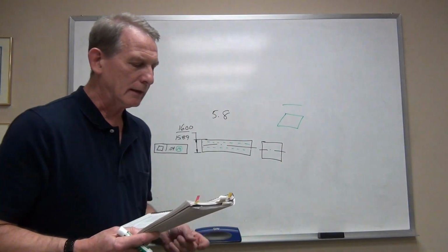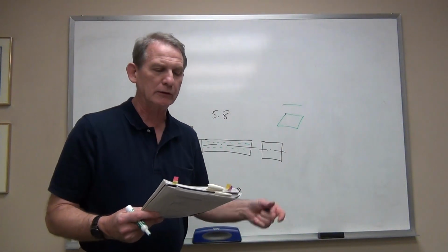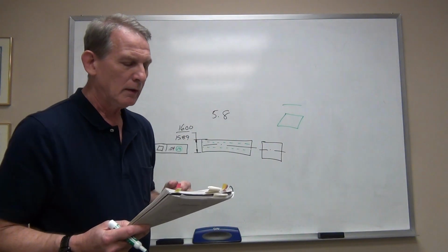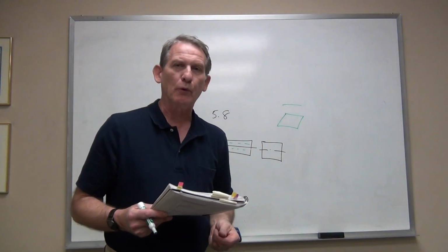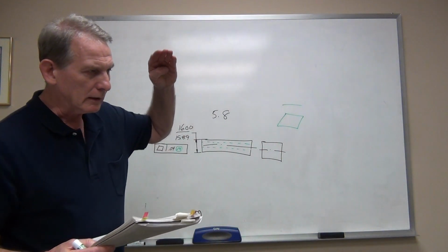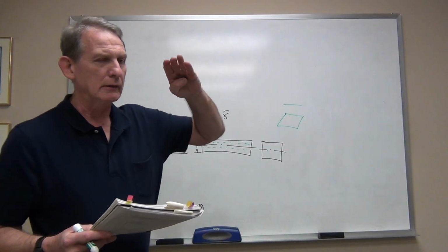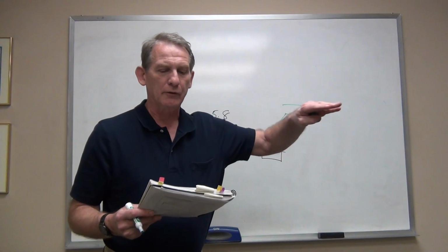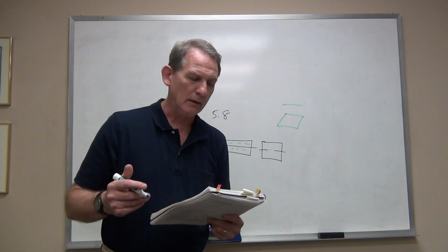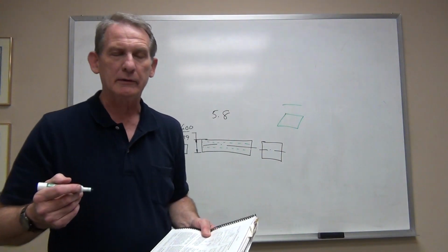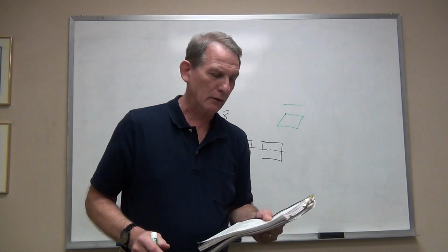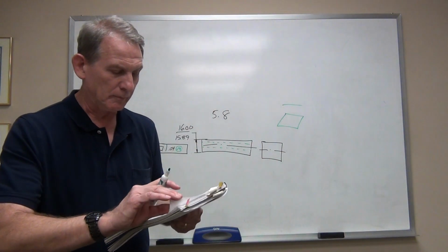In other words, if the bar is at its maximum material condition, which is 16 millimeters thick, then you only get 0.04. As we get smaller and smaller, in other words, as that bar gets thinner and thinner, the derived median element gets more and more tolerance for being not flat. And you can sort of follow that along in the example.